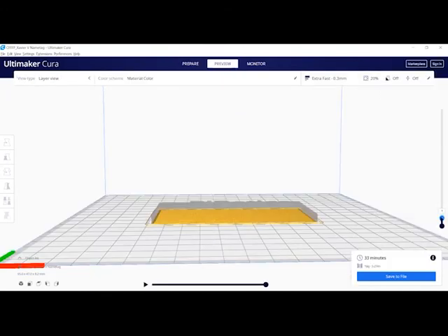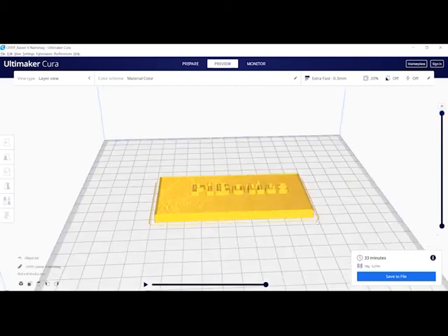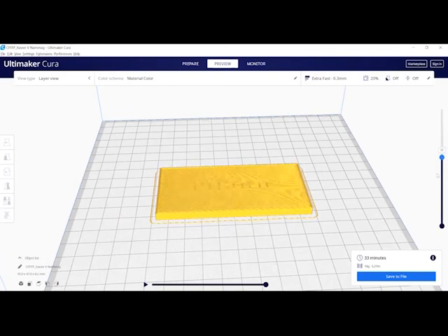This is what it looks like while 3D printing. As you can see, it's very important that because layers stack on top of each other, nothing is floating in midair. This allows our prints to be made successfully. One way to help with top layers is by having infill. If you want to have parts hanging in midair, you need to specially design your part so that way it'll allow for the 3D printer to easily transfer over these areas.